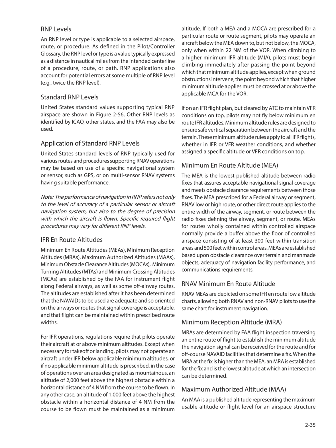Minimum reception altitude, MRA. MRAs are determined by FAA flight inspection traversing an entire route of flight to establish the minimum altitude the navigation signal can be received for the route and for off-course NAVAID facilities that determine a fix. When the MRA at the fix is higher than the MEA, an MRA is established for the fix and is the lowest altitude at which an intersection can be determined.